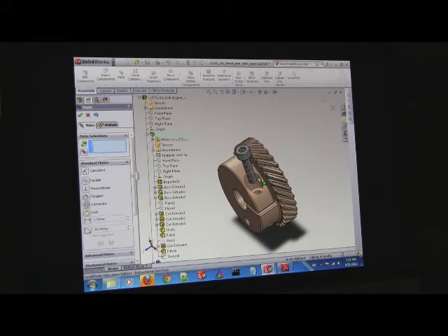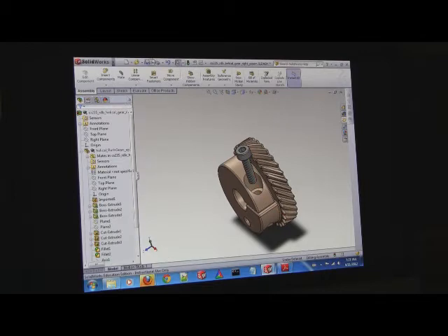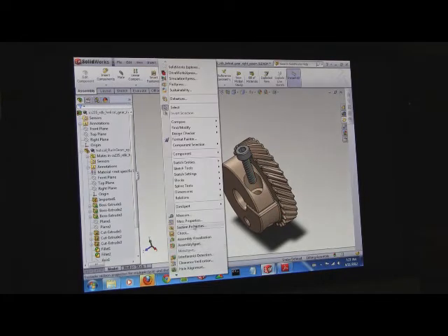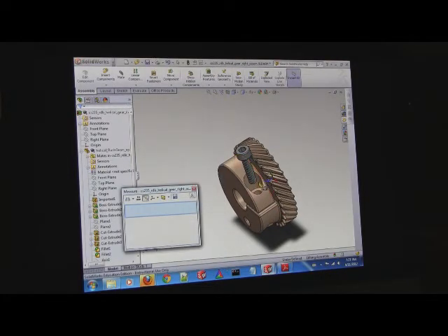But you made this part and you can see this part. You can also measure it. Shruti, if you want to see if it really truly is concentric, go to Tools, Measure, and click the outside hole and the inside hole. And you see how it says delta x and z is 0. Distance between central axis is 0. That's how you tell for certain it's concentric.